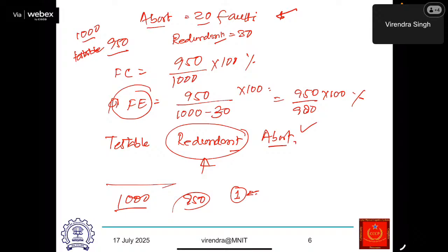Now the question is, should I keep running for this particular fault and let it decide whether there is a test vector or there is no test vector for this? And that may take any amount of time. I have no idea how much time it will take, because in the worst case it can take 2 raised to the power of the number of inputs, and that is a humongous number. So what we do is, after a while we put a limit on time, that if this much time has expired, you say that perhaps there is no test vector for this particular fault, this might be a redundant fault, and therefore abort the generation of the test for this particular fault.